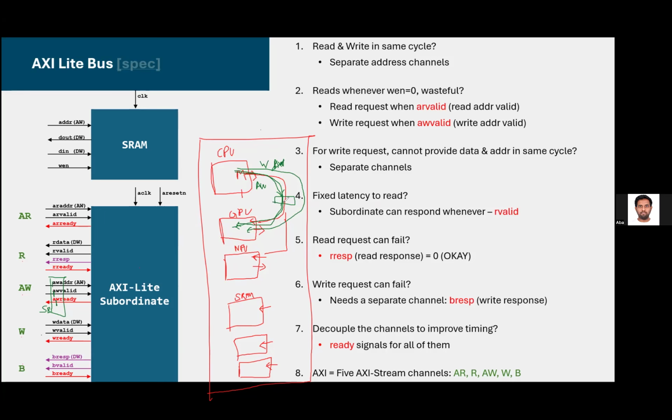And that is completely fine according to the AXI standard. The standard is written to handle this kind of situation, so that you can pipeline each of these 5 channels independently. You can put registers and skip buffers into the 5 channels independently, so you are not affecting any of them. They don't have interdependency in that case.